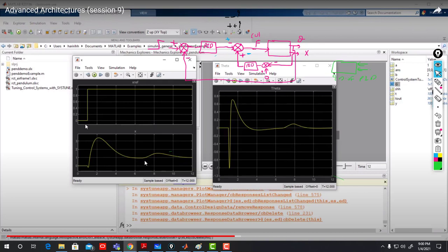So then in our inverted pendulum at the lab experiment, we don't even have that distance, we don't have 3 meters. So then also a step doesn't work unless you have a smaller step, not 1 meter, maybe put 0.5 meter or 0.3 or 0.25 meter, so then it works.